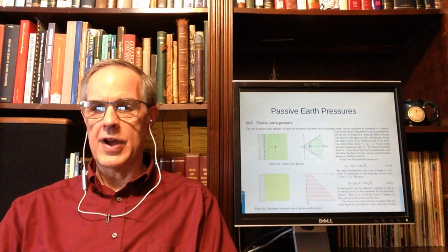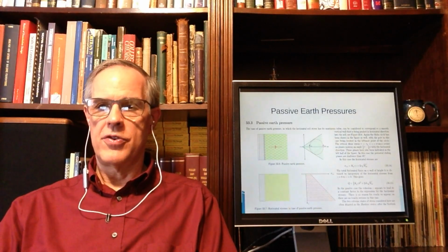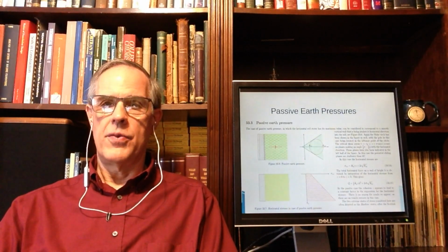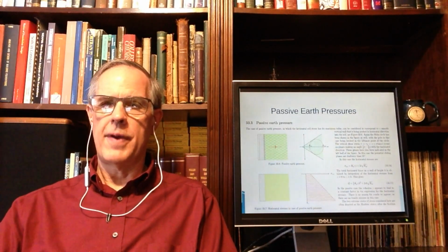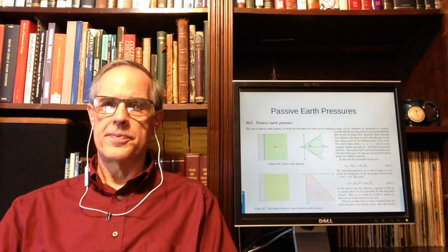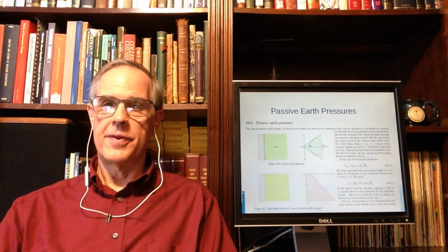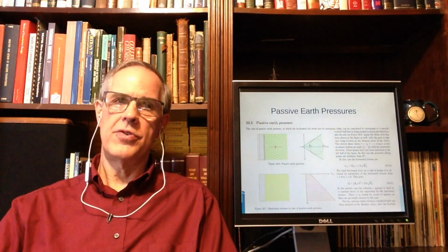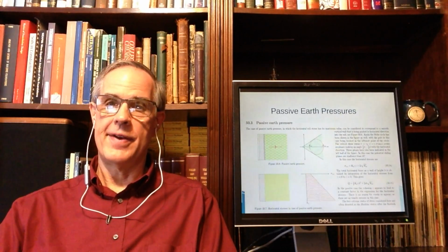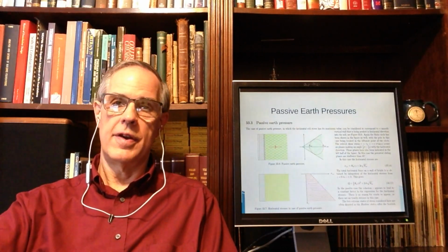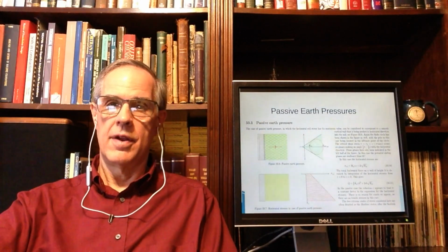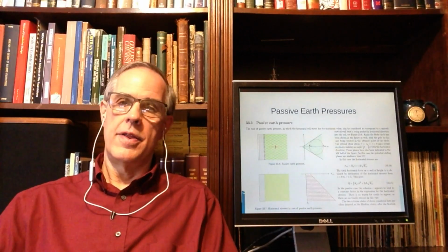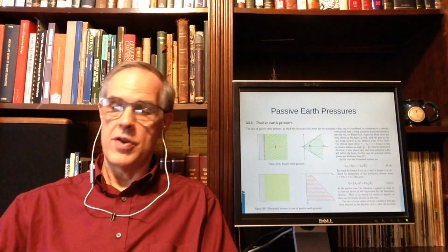Passive earth pressures are just the opposite. The wall pushes into the soil. The passive pressures are much higher. And the only place we're really going to deal with passive pressures is with sheet piling, because with sheet piling they're absolutely essential to keep the wall up. We do see passive pressures. In many cases we discount them. They're just not significant enough, and they just add to the uncertainty of our calculations. And again, you see here the inclusion of cohesion.